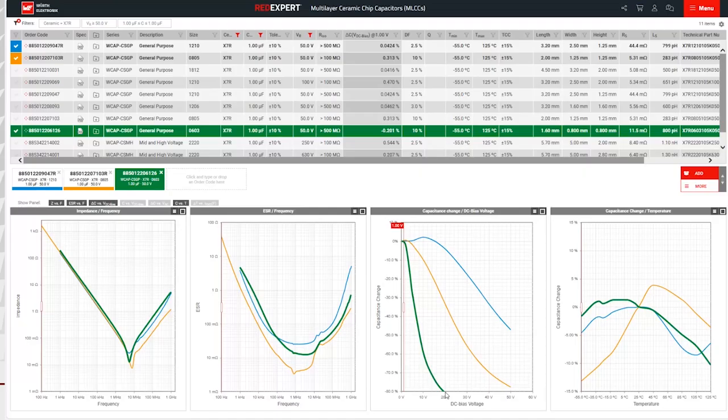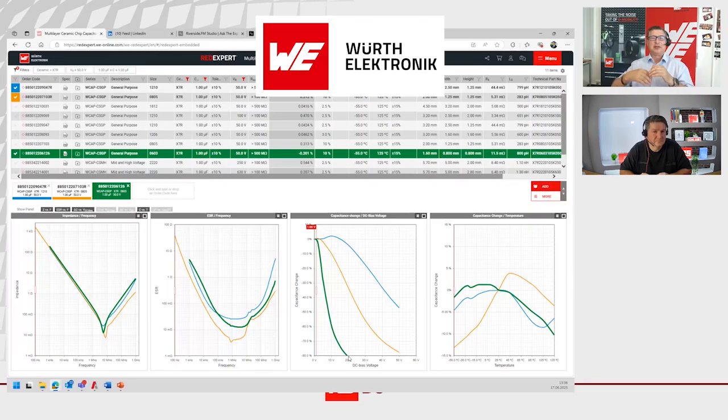And then you're wondering why your DC-DC converter ripple is not dropping, or why you have EMC noise, because it's still the capacitor you put there. And then you think, oh, I have to put more of them. So instead of putting 10 pieces in a row, choose one of the right size, because it's not only the data sheet, it's physics, it's the behavior of this dielectric.